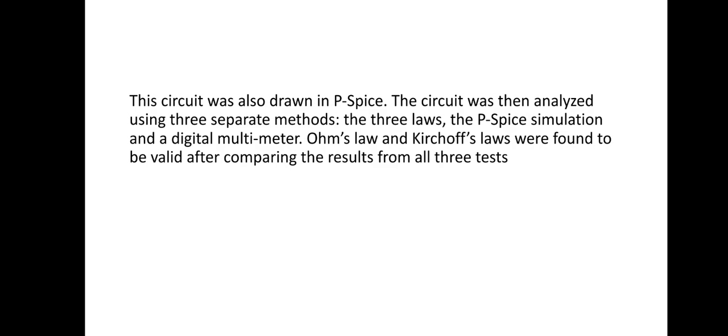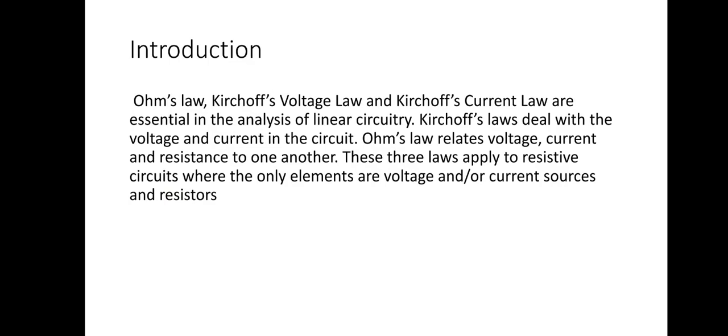An electrical system can be modeled by an electric circuit, a combination of paths each containing one or more circuit elements, if the dimensions of the circuit are small compared with the wavelength of the electromagnetic waves in the vicinity, that is, wavelength lambda equals c by f, the physical dimensions of a system, where c is the velocity of electromagnetic waves and f is the frequency of the wave.